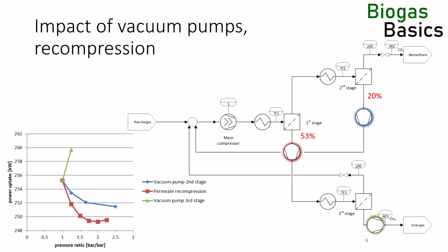But the off-gas volume flow is defined by the biogas inlet flow. The outlet pressure of the stack is ambient pressure. Neither flow nor pressure at the end of the stack can be manipulated with an inline blower. The correct installation of this blower is to suck in air from the environment and commingle it with the off-gas before it is expelled from the stack. This increases the velocity in the stack and premixes the CO2 with air, which lowers the density of the expelled